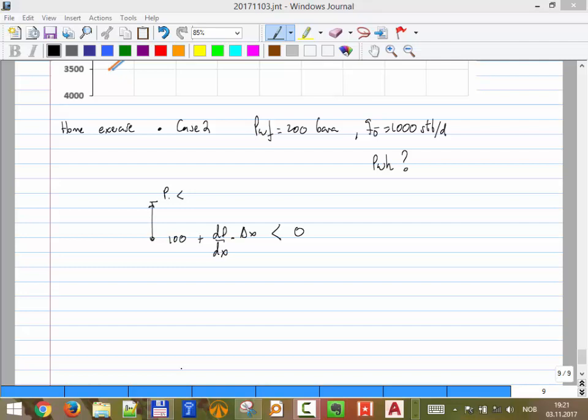you have critical flow, where you have Mach number 1 in the throat, sonic velocity. Then we talked about liquid. Liquid you already knew, but it's very useful for emulsion and for undersaturated oil. And we saw the effect of temperature, that you actually have to discretize to see how viscosity and density change along the tubing.